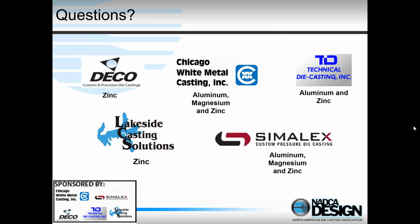So zinc is the lowest heat load on the die, so it lasts the longest, and I'm going to say 500,000 cycles, 500,000 shots, something like that. For aluminum, aluminum is the highest melting point and it's most aggressive on the die. It used to be, maybe now people are getting up to 200,000 shots as we use better steels and we understand the heat treatment, and also how to look after the steel with a good casting design. And so somewhere between that is kind of a good number for the life of an aluminum die casting die.